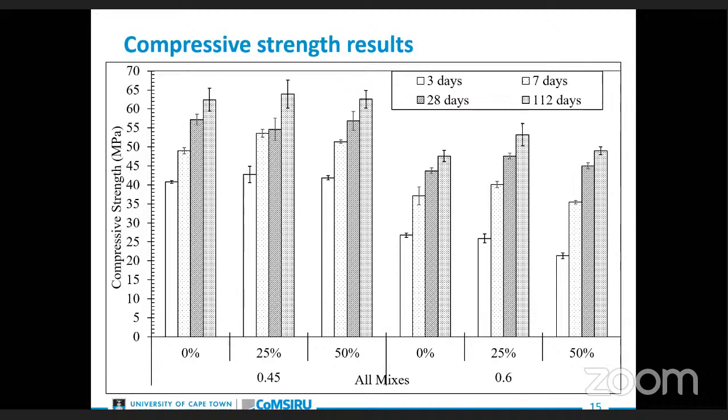In addition, at 50% replacement level, early age strength is lower, but quickly increases by 28 days and is slightly higher than the 0% replacement level at 112 days. These results could be inferred from some of the literature that suggests that since RFA can store more water, this water can be released into the new concrete and over time continue to feed the cement for a longer period of time, which increases strength. Hence it is possible that the hydration process progresses further with replacement of RFA at 25% due to these results.